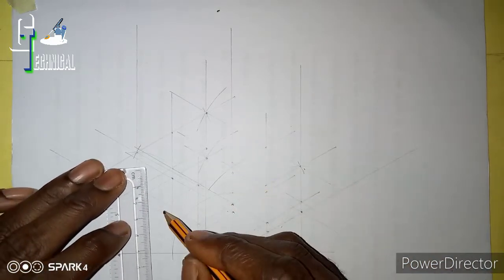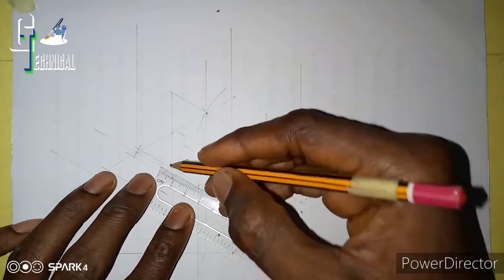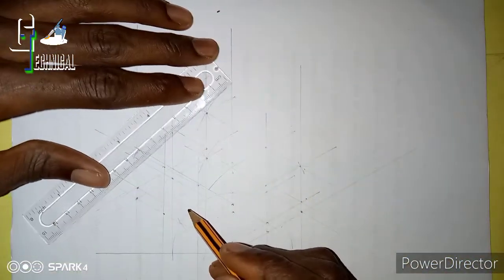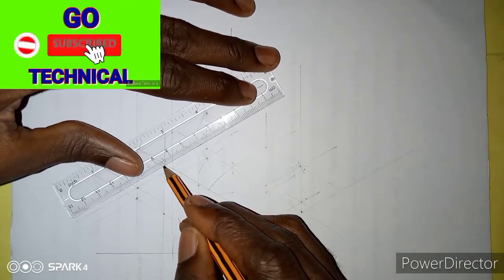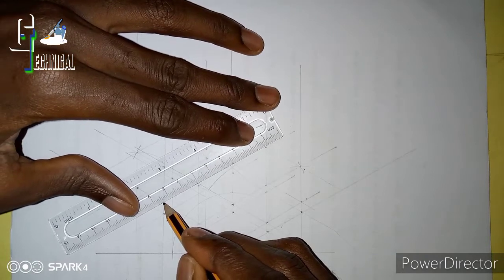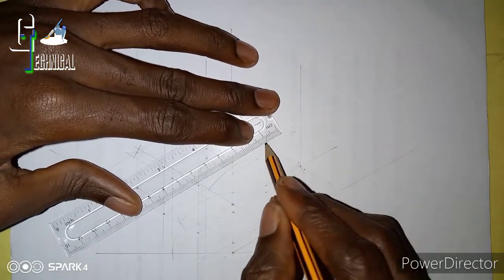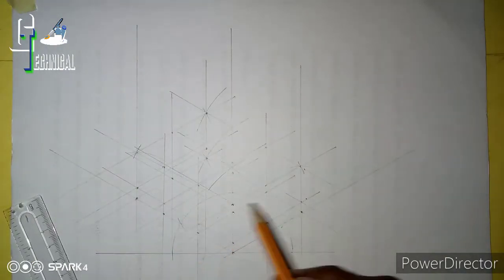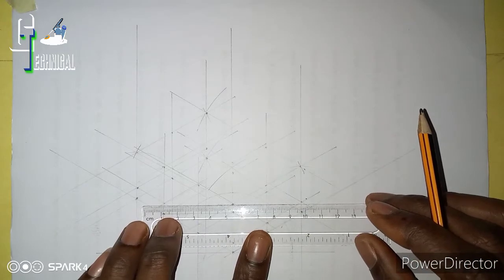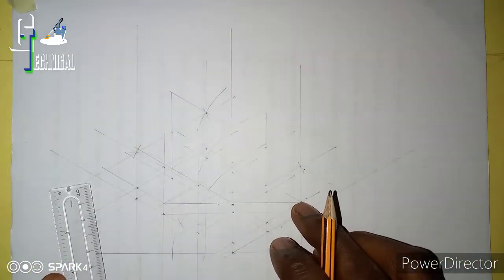So we have this line. Now we also take this other one from here. So we have this point as 50. We project. This one is already there. Now we join this. Join this. And we also join this, this with this. Okay. So now we have gotten a box. So with that box, we have to draw a line this way and draw another line this way. So now we use this to draw our isometric circle.